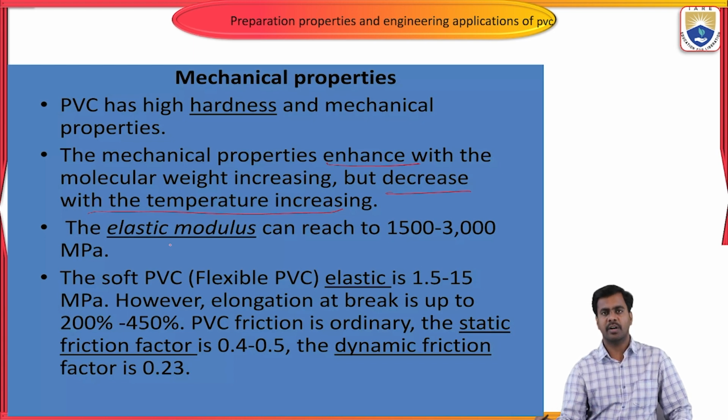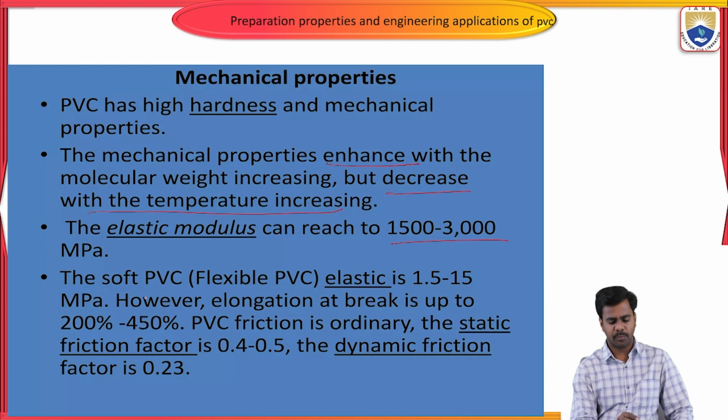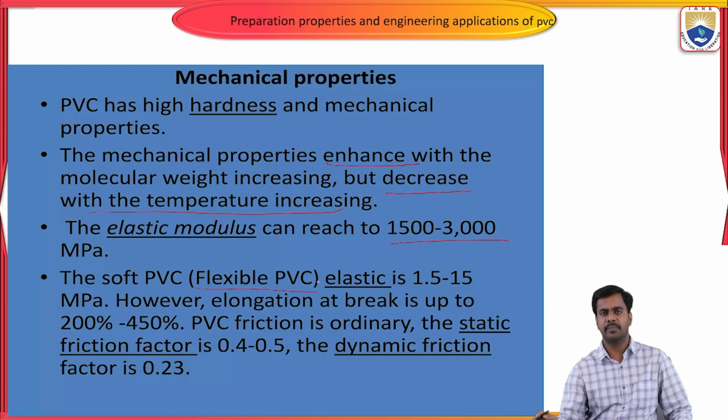The elastic modulus can reach 1500 to 3000 MPa. For the soft PVC, that is flexible PVC, the elastic modulus is 1.5 to 15 MPa.